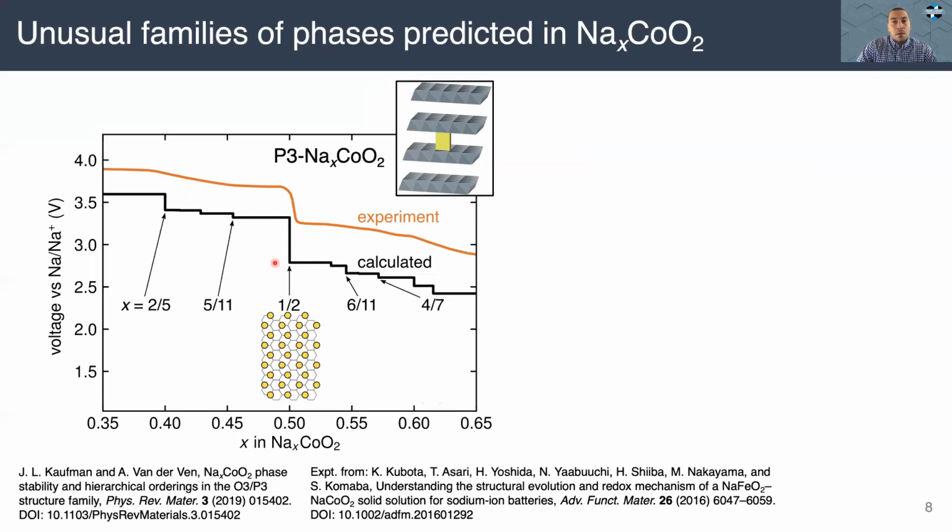Then what I predicted is that as the composition decreases, this ordering is actually retained locally, and vacancies are introduced as antiphase boundaries between domains of this ordering. And at even lower concentrations, it's the same, but the density of those boundaries just increases.